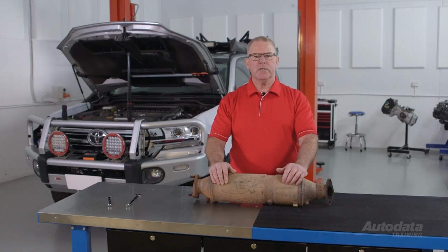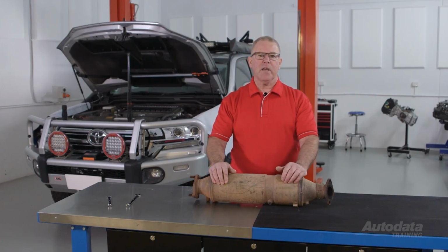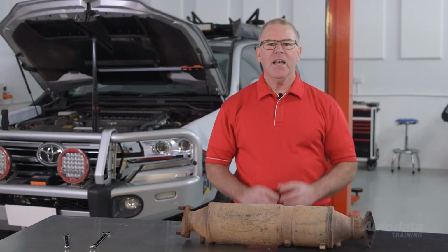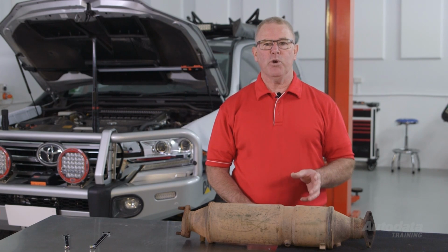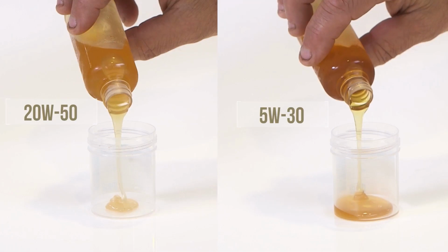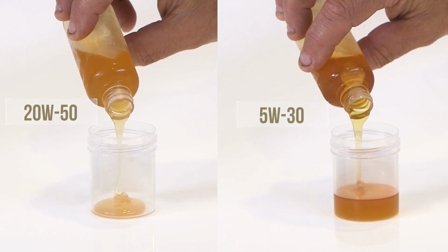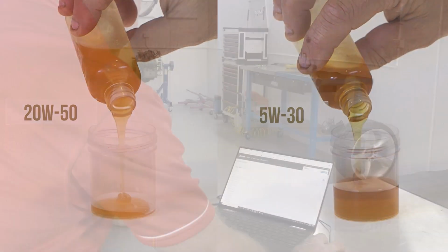From my experience, unsuitable driving habits and lack of understanding cause the most DPF regen faults. Understand how the DPF systems work and educate the driver. They may have to change their route to work a couple of times per week to initiate a passive or active regen. Use a good quality engine oil with the correct viscosity and service classification for the engine.